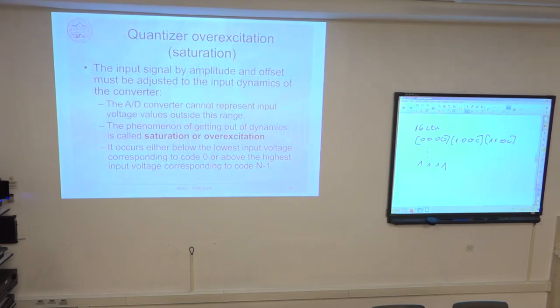And sometimes it means that this voltage reference is also thermally stabilized in some kind of closed loop. It has some heater that constantly keeps the thermal reference at the same temperature, for example, 40 degrees Celsius, whatever the outside temperature is. So it has some kind of closed loop regulation that ensures that this reference silicon chip is kept at the same temperature. So in this case, the value is guaranteed to be within 1 per mil around the nominal value and so on. Okay?